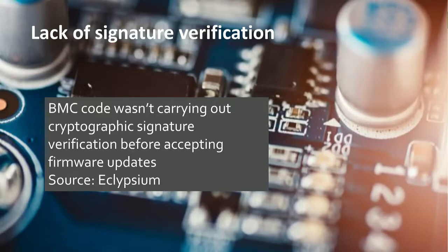Sure. If the payload that is delivered to the BMC, whether it's firmware or configuration changes or OS patches, if they're not code signed by the supplier, then you really don't have a way of verifying that payload is authentic. But if it were to be signed by the supplier, the BMC code has to verify the signing. And verifying the signing is a process that requires the public key of that PKI to be on the device.